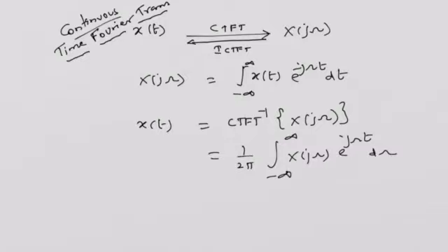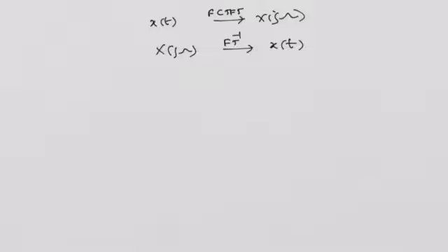So this is the usual method of obtaining the Fourier transform and inverse Fourier transform. Given x(t), obtaining X(jω) is called the forward CTFT, or CTFT in general. Given X(jω), obtaining the time domain signal x(t) from the spectrum is called the inverse Fourier transform. It is called CTFT inverse. You must understand these two in general before proceeding with the new problem.